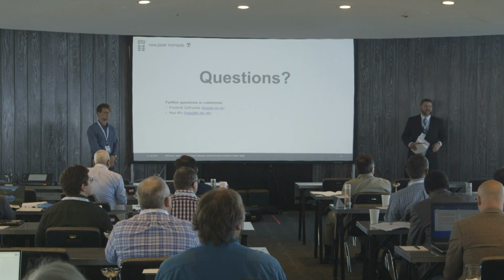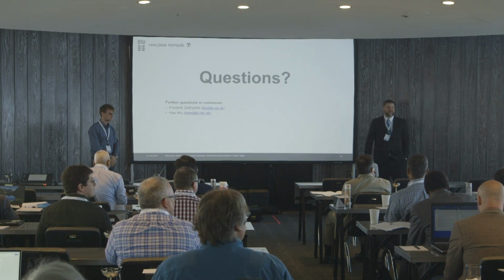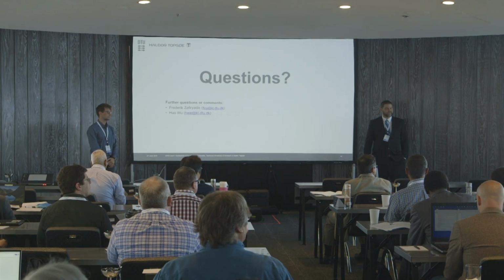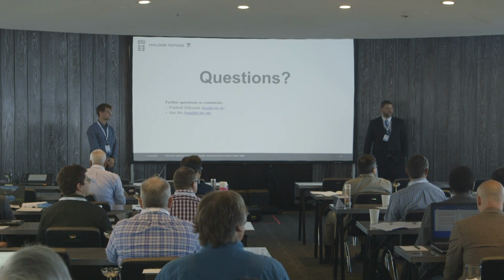Okay, so, sorry. You showed profiles at different elevations in the riser, right? In the riser, at the wall, you have close packing. Solid volume fraction at the wall around 0.6 or so. Do you believe that? Have you tried to compare with literature data? Because I think at your scale you may find some.